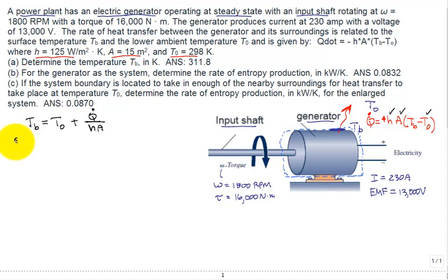And so in an energy balance, all the ins must equal all the outs at steady state. And our inflow is by this shaft power. So W dot shaft coming in. How about an out? Well, W dot electric. We want as much of that shaft input power to be converted in the generator to electric power and come out.